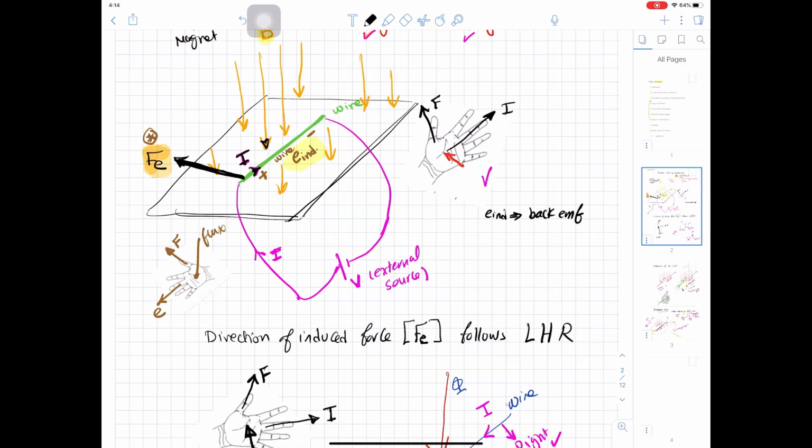So you can add to Newton's law that if there is an action, there is a reaction from the same nature, which means if the action is mechanical, the reaction is mechanical. If the action is electrical, the reaction is electrical. So here you injected current I into the wire, so the reaction has to be electric. So the wire has to react to this current in an electrical reaction. To get this electrical reaction, the wire will start to move to generate this E. And if you can see, this E is against the current. It consumes the energy from the current. So this E opposes I.